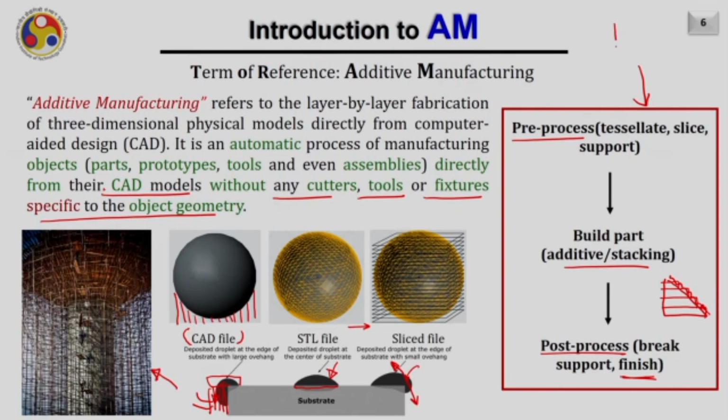If you are going to make this cylindrical object which has a 6 mm diameter hole over here, and we are going to produce this part by lathe operation, on the lathe machine, you need a 3-jaw chuck to hold this object appropriately and a 6 mm diameter drill bit to make this hole.